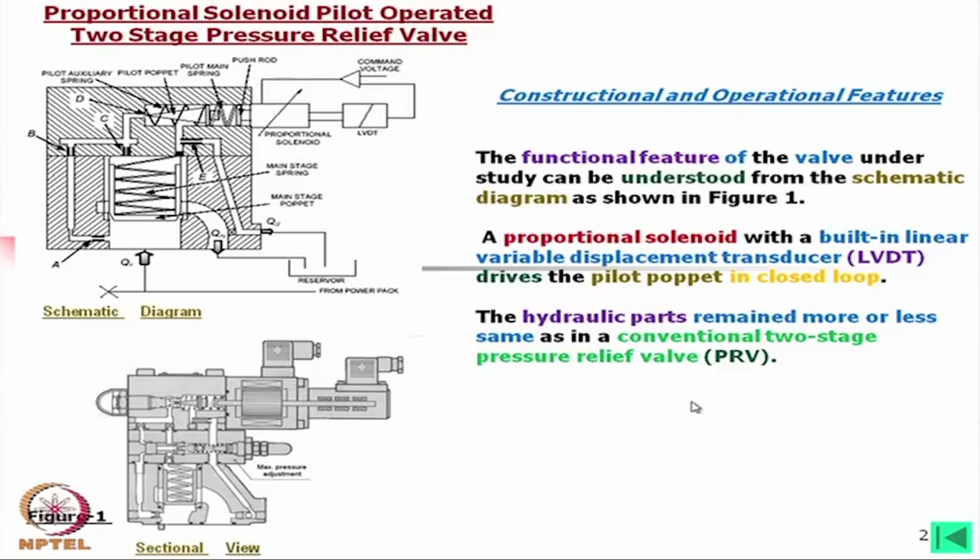Normally, we call pilot operated pressure relief valve POPRV. O is small, all other capital. The next lecture I will describe that also. So, here again it is solenoid operated. So, for that no this abbreviation term is there. Normally we call it proportional PRV, simply, but once it is a proportional PRV, it will be POPRV, proportional pilot operated pressure relief valve, that you should remember.